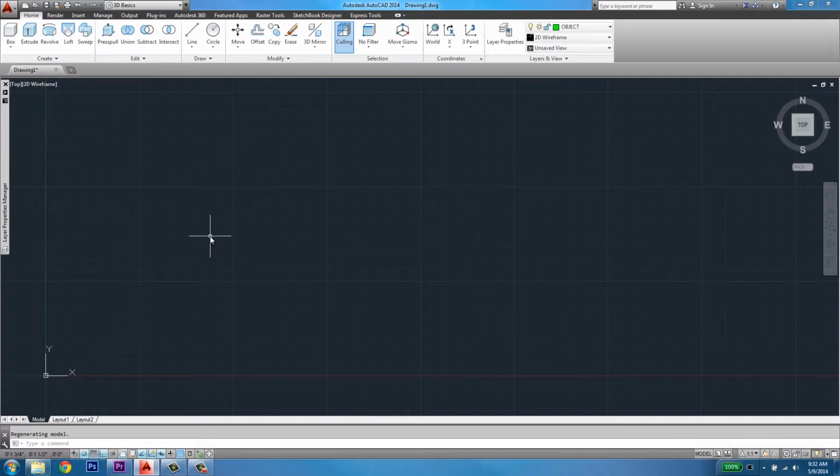The first method is using your mouse only with the grid as a guide. To begin, select Line or Polyline. Remember that it helps to have your snaps on when using this method. Another helpful function is Ortho, or F8 on your keyboard. If Ortho is on, you can only draw vertically or horizontally. Click a start point and an end point for each line.